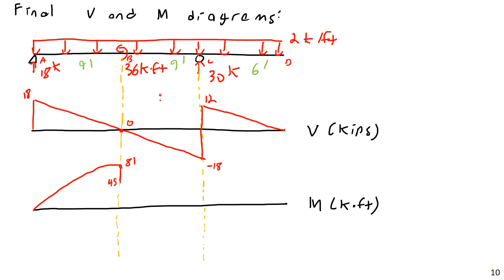And this is interesting. I always find this interesting, and it's kind of hard to wrap your head around at first, but it makes sense when you think about it. Notice this applied load, what direction is the applied load? It's positive, right? But it causes a decrease in the internal moment. The reason is because internal moments balance exterior applied moments, so they have to be equal and opposite. So if I apply a positive moment, I get a drop in the internal moment, because shear and bending moment functions show the forces that are interior to the member. They're the forces that are fundamentally resisting all of the external loads.